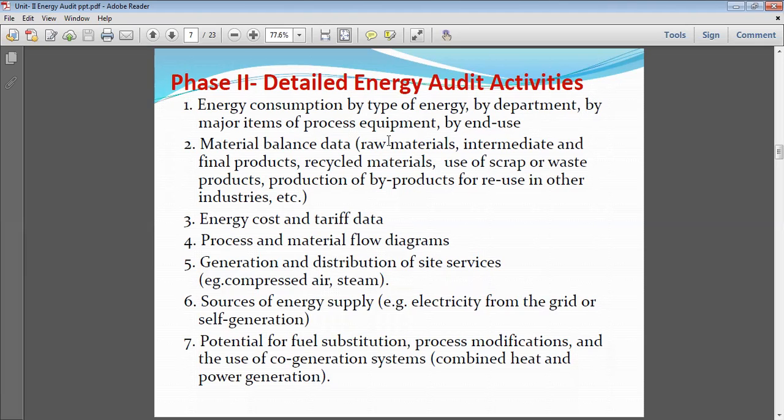So continuous losses are there to decrease the temperature from 15 degree to 10 degree, whereas the requirement is only 15. So therefore, it is necessary to understand the layout as well as the recommended values for the different applications. What temperature is needed? What is the hot water? What compressed air is needed? If you are using more than that value, definitely there are losses.